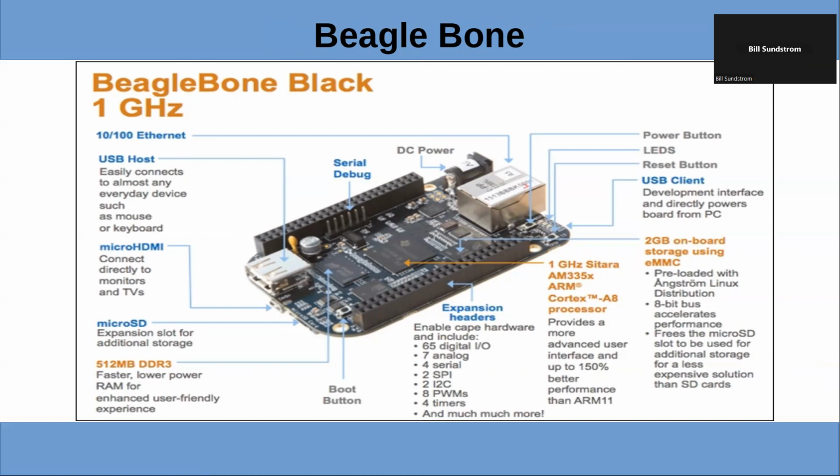In the case of CNC control, to drive stepper motors. So you can generate the 1 microsecond pulses and direction controls, and read encoders, things like that. I've had one of these running 4 axes and 2 encoders, and there was some other stuff. Didn't miss a beat, could run about 100 inches per second cutting. Which always scared me.